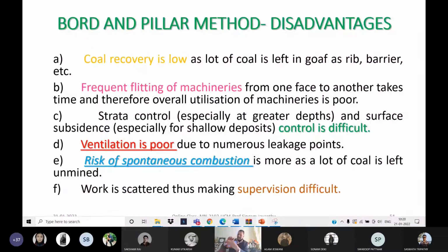Along this diagonal line, if you are unable to excavate any pillar in between because of some fault or slip plane, slickenside, whatever, depending on the discontinuities, and I will show so many things through case studies later, where that part is left out, this side is destressed, this side is destressed, and there will be stress concentration. That causes a lot of problems.